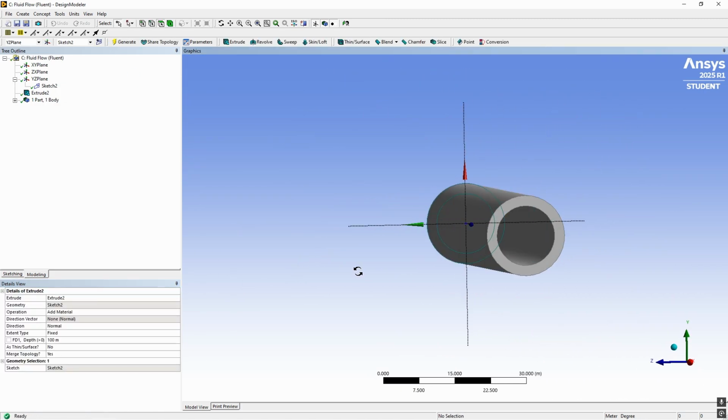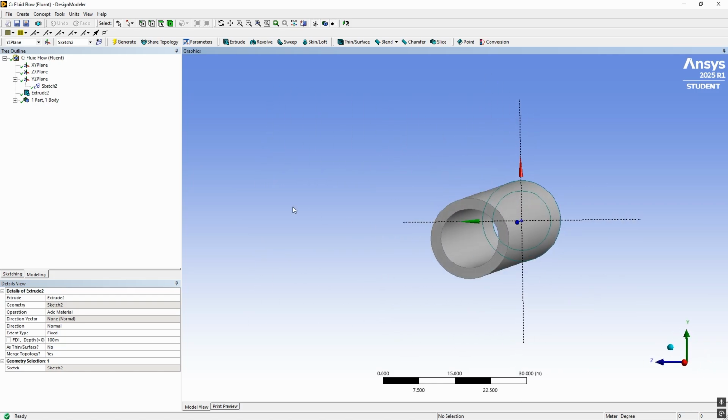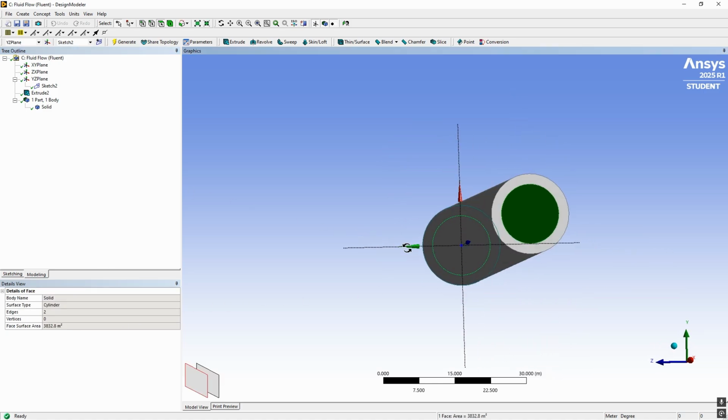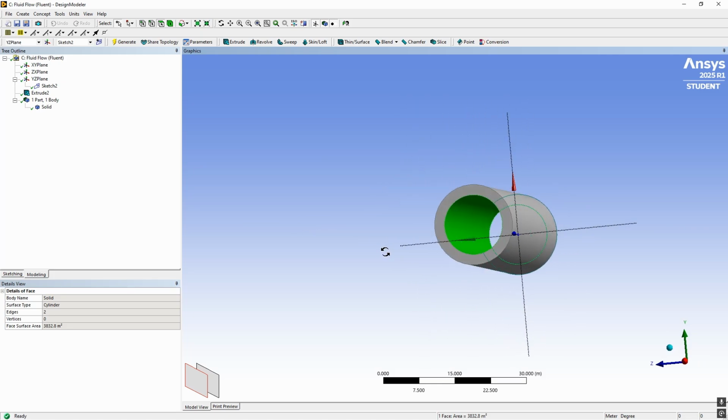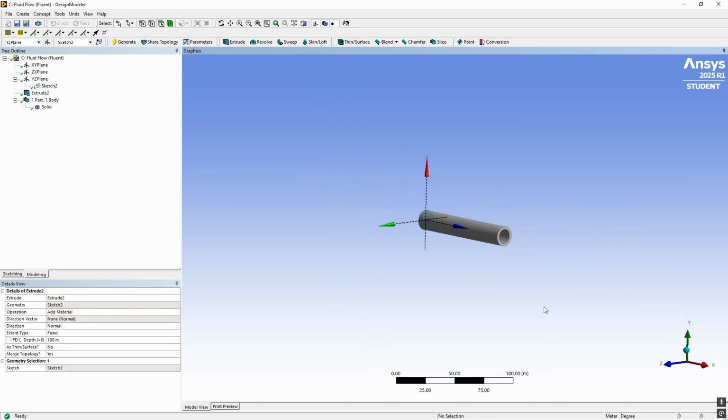Now you have this hollow pipe and you want to analyze the flow inside this hollow pipe. We have this solid body, but we don't have the internal fluid. Normally you can just draw this internal part of it and carry on your simulations. Just model the internal fluid part. Here I draw a very simple part, but imagine you have a very complex one. Let's say this comes around here, goes up, goes left, goes down, so on and so forth. And you don't want to model that entire complex thing again in the CAD model.